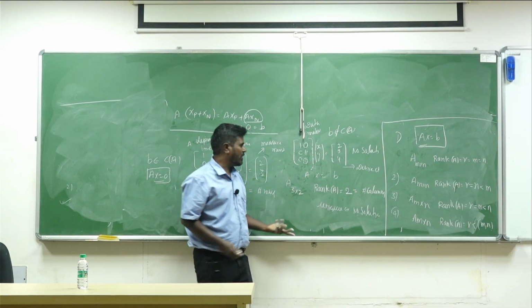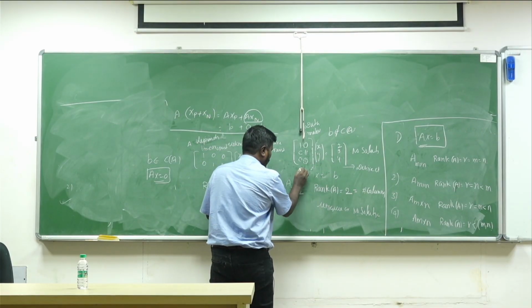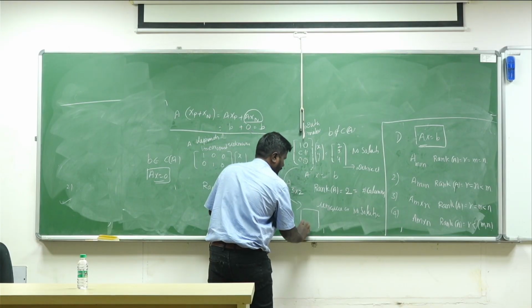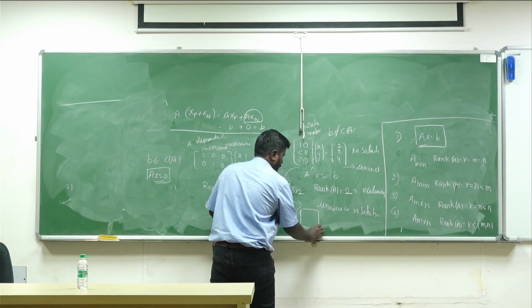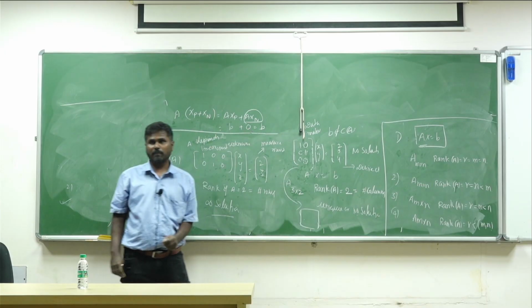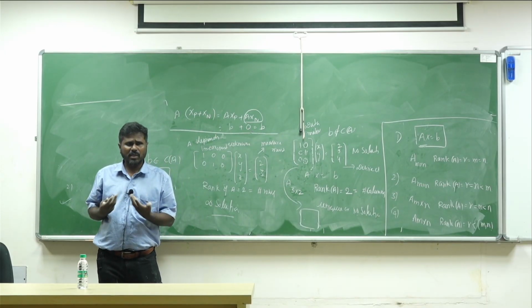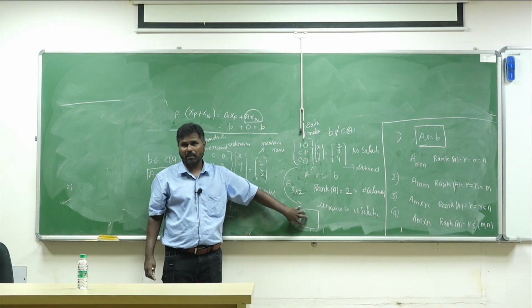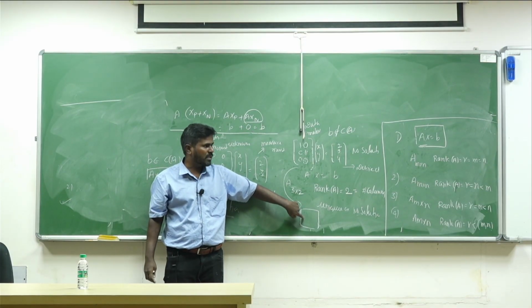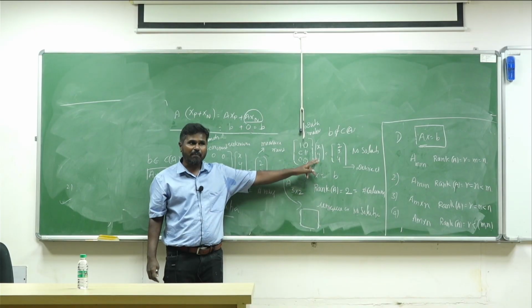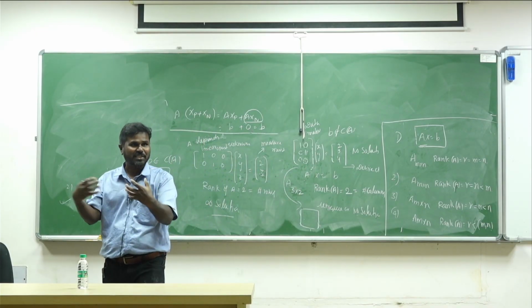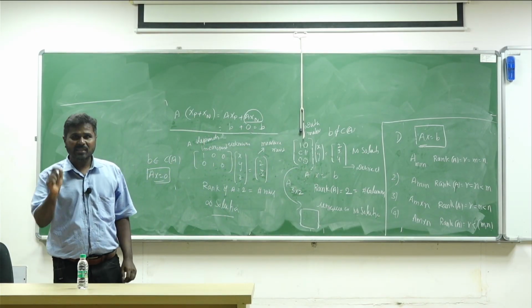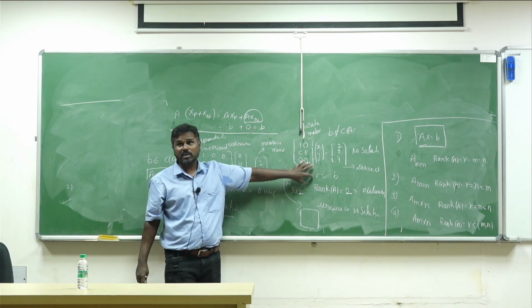This may be a problem from the design of the Wiener filter. The number of parameters that we want to find for the Wiener filter is less than the number of samples that we receive. That is the reason this is the overdetermined system.